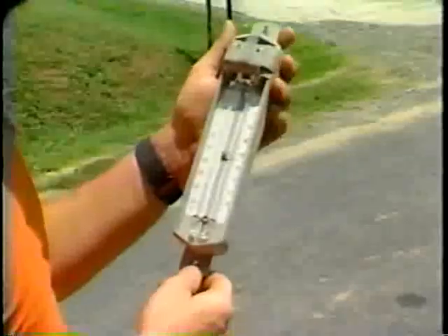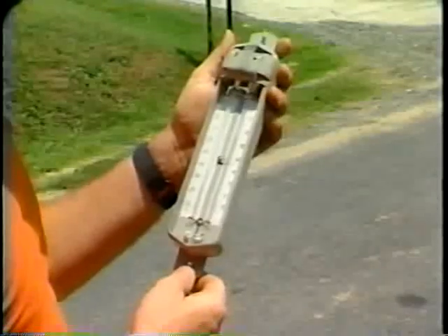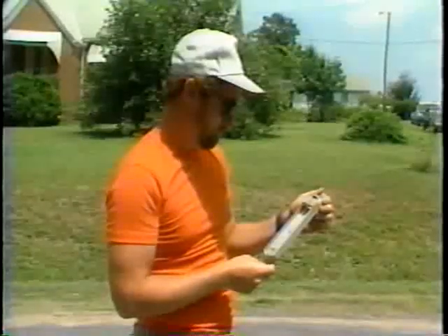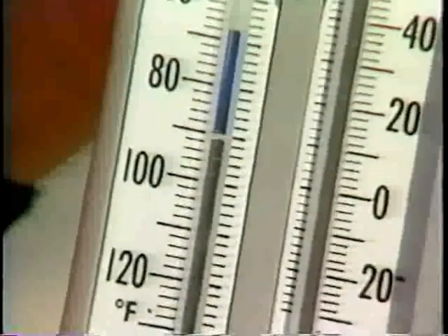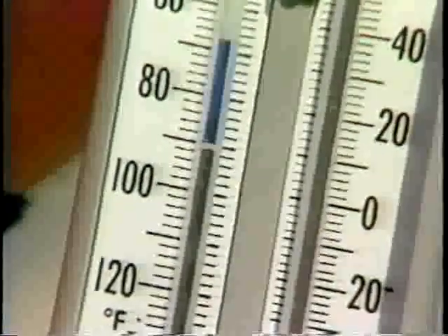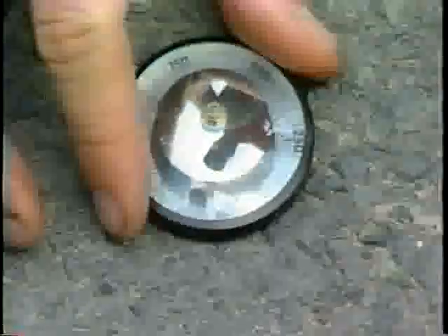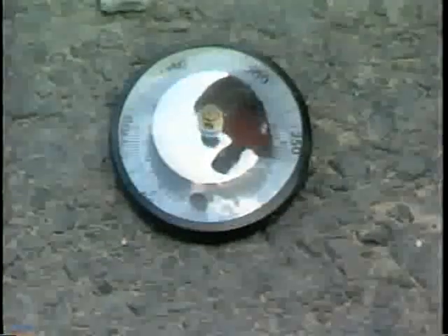Proper weather conditions are extremely important for an effective chip seal. Hot and dry weather is ideal for performing seal work. Do not schedule work if the air temperature is below 50 degrees or if the pavement temperature is below 70 degrees.